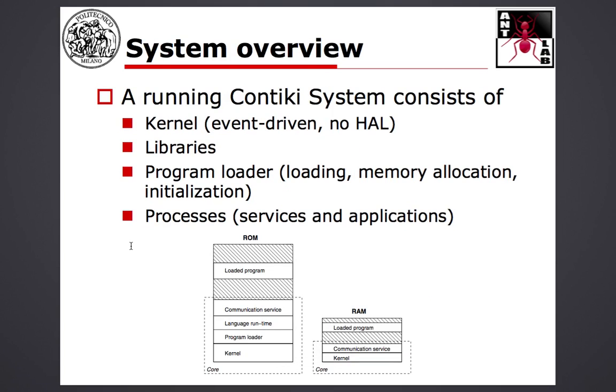Now let's see very, very quickly a system overview. As I was saying, the concept is a little bit different from TinyOS, and I would say more similar to ModeRunner, even if we do not have a virtual machine here. Okay. So I would say both the ROM memory, so the part where the code is stored, and the RAM memory, so the part where the variables are stored, are divided in two parts in Contiki. Okay, so we have a core part which stores the information for the operating system, and then we have a part which is free for your processes. Okay, and that's basically the part that you modify when you dynamically load a new process.